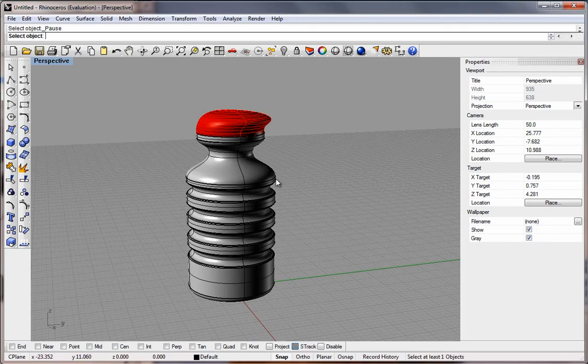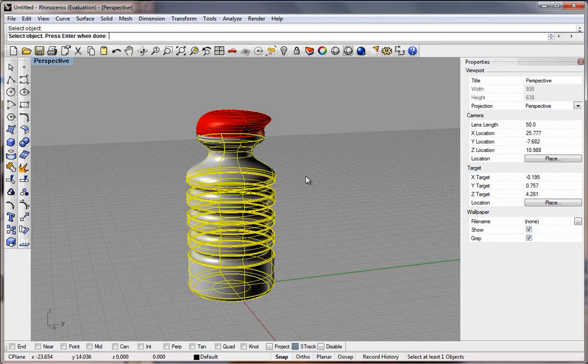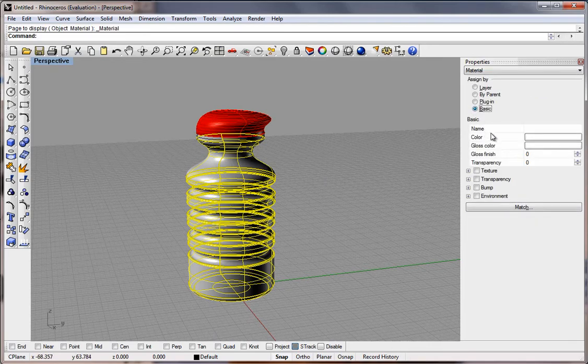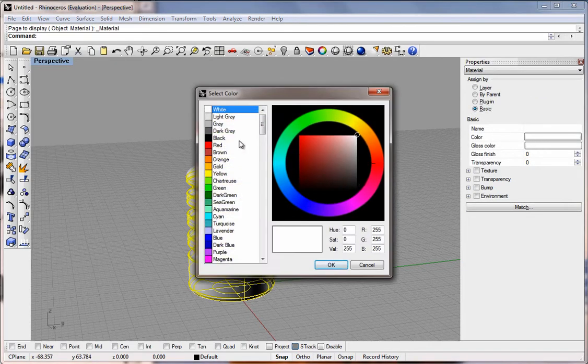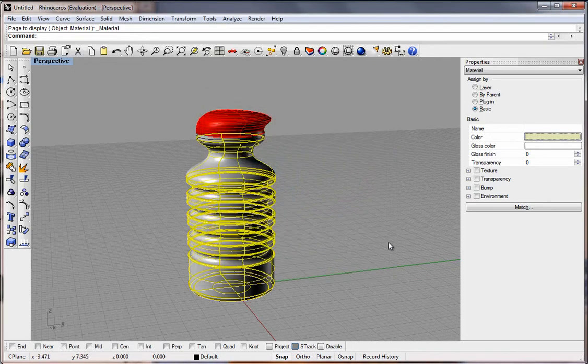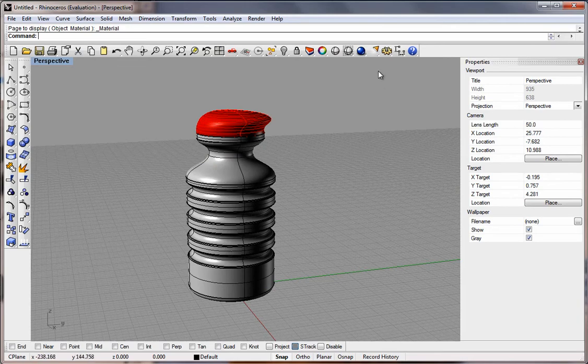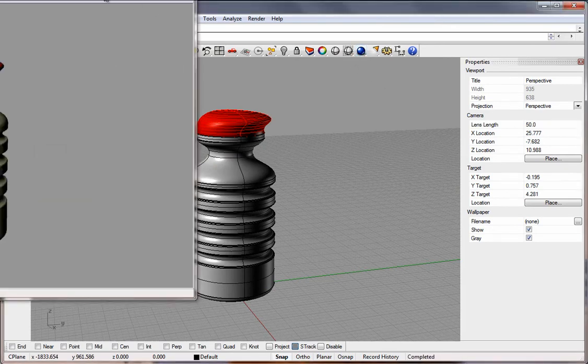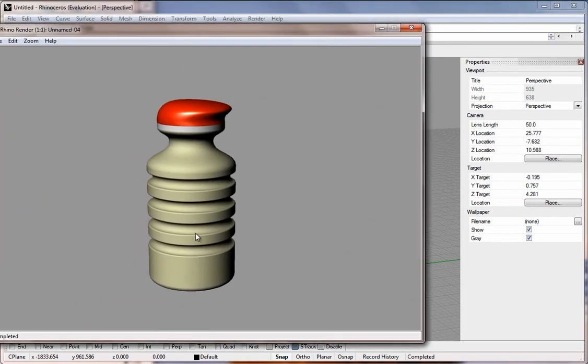And now go right click again and select this body. Right click, basic, color. And this one's going to be kind of like a cream color. So if we go with the off yellow a little bit there, a beige, and hit enter. Now you don't see them update right away. It isn't until you actually go to the render tool that you can see it update.